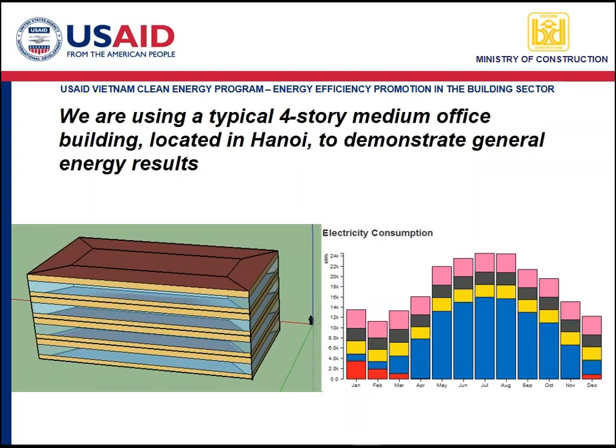So the core zone only has loads from people, from lights, and from equipment. It's very different from the perimeter zones, which have losses and gains through the walls, window, and floor. So we analyze the perimeter differently in the computer program.